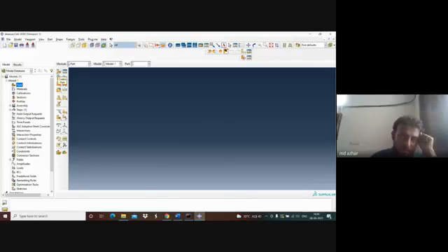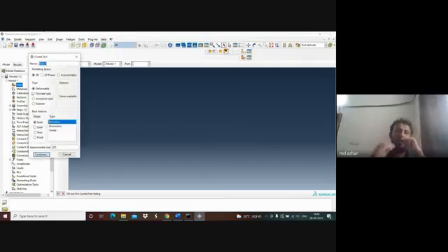There are different ways to prepare geometry. Let us just start, and we'll click on create. Here you can see three-dimensional, two-dimensional, and axisymmetric. You have to understand each. Suppose you are making a geometry in three-dimensional. Then you have extrusion, revolution, and sweep. This is basic CAD which you might have done in the previous classes. If you are making a geometry in two-dimensional, there is no extrusion, no revolution, and no sweep option.